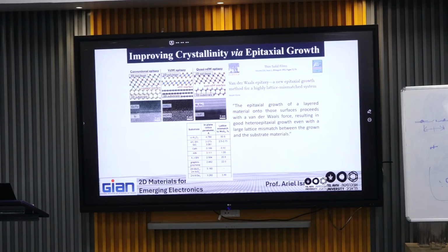Hydrogen reacts with carbon, forming hydrocarbons, so therefore gasifying the impurities, and also by introducing very small amounts and for a very short period of time of oxygen or water vapors. The oxygen will react with the carbon leading to CO2, therefore cleaning the surface from the carbon.